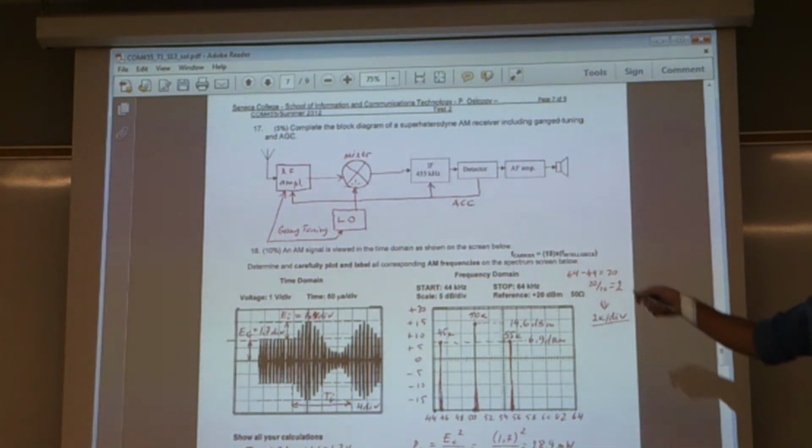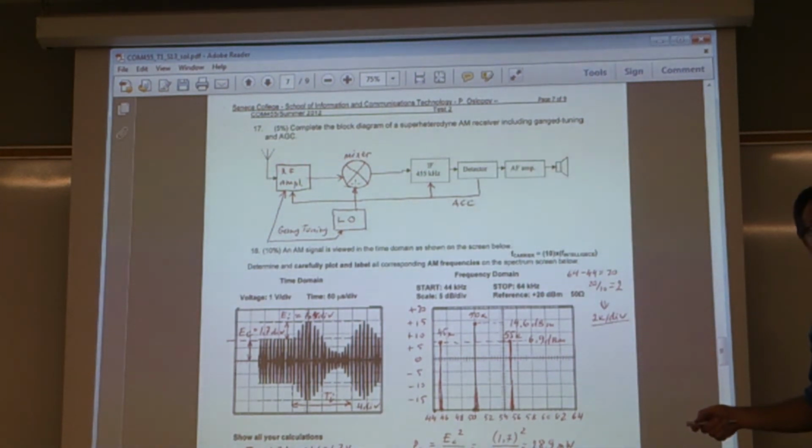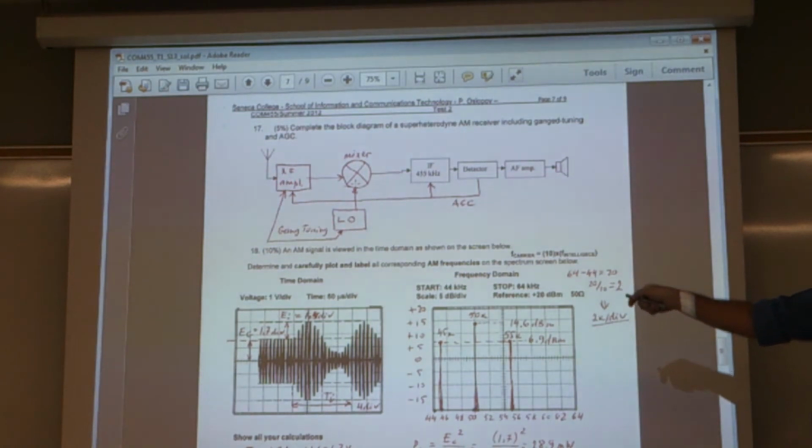How do you preselect this channel? You tune it. And tuning is ganged. That means whatever the LO and whatever the preselector, they share together a bank of tuning capacitors, or whatever variable element is used, to tune to the different frequencies. That's really my game.